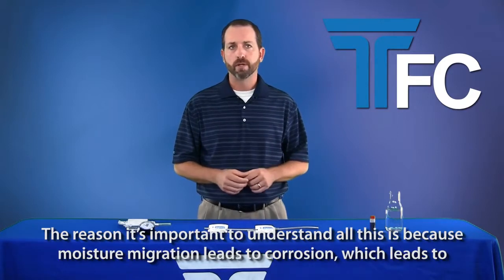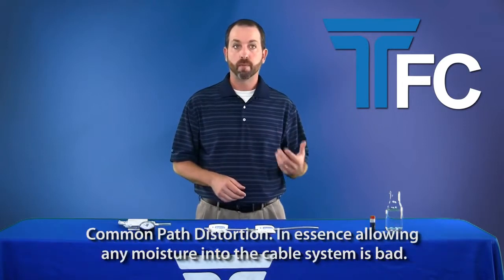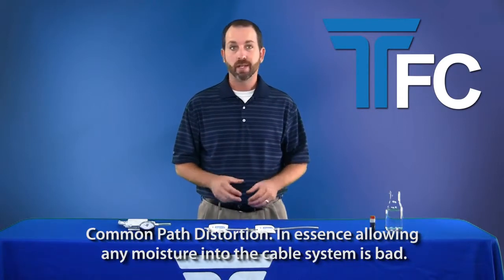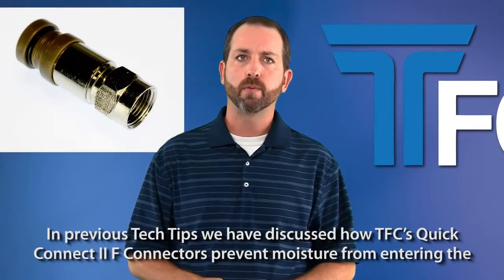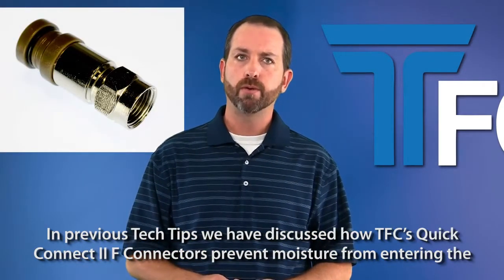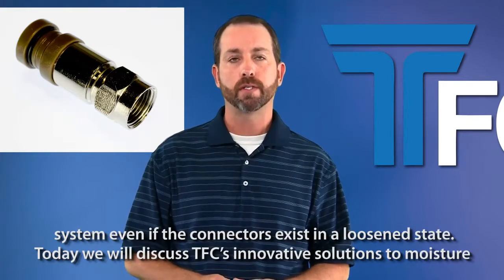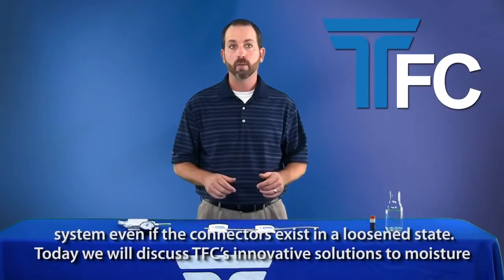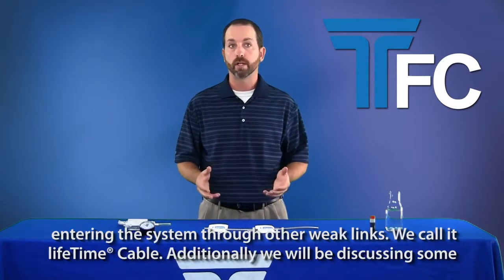The reason it's important to understand all this is because moisture migration leads to corrosion, which leads to common path distortion. In essence, allowing any moisture into the cable system is bad. In previous tech tips, we have discussed how TFC's Quick Connect 2 F connectors prevent moisture from entering the system even if the connectors exist in a loosened state. Today we will discuss TFC's innovative solution to moisture entering the system through other weak links.